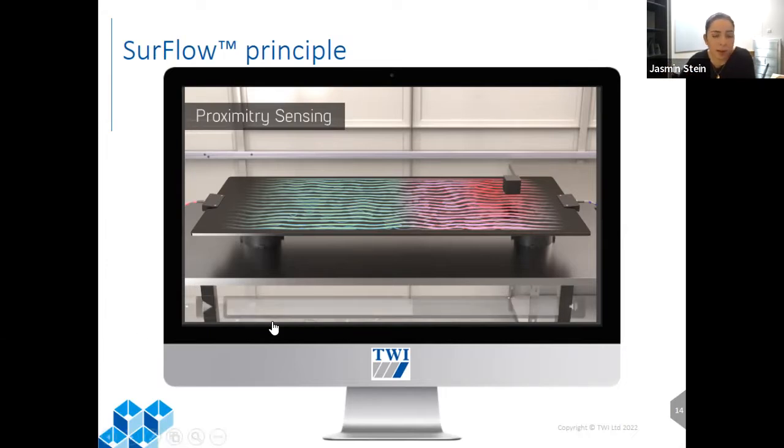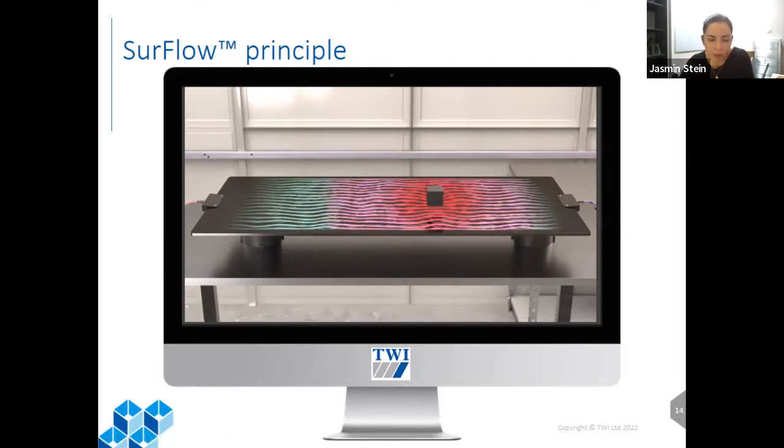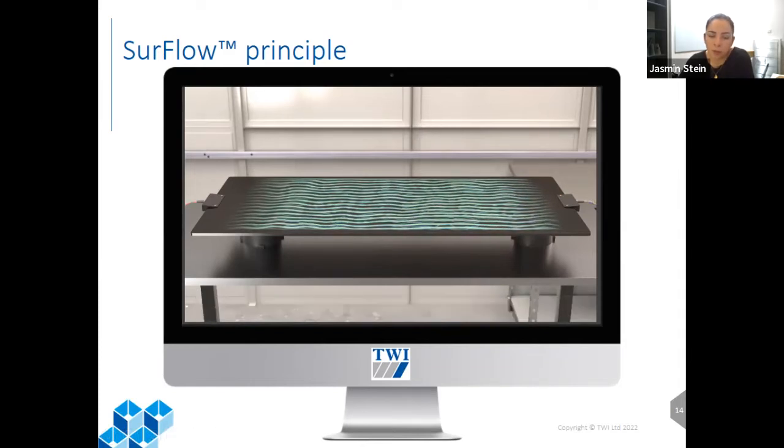But also, we have something called an evanescent field coming off the surface. By bringing something into close proximity of the surface, the evanescent field gets slightly affected. You still get the full data, but the signal signature has changed. And therefore, you can also use this composite, or the surface wave material, for proximity sensing. However, there are many things to be thought through. What sort of distance are we looking at? And in that case, what sort of frequency do we want to use?